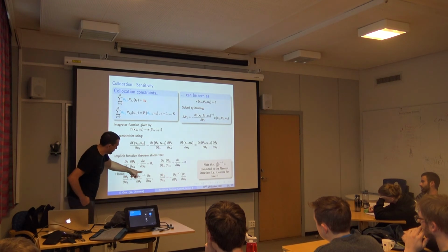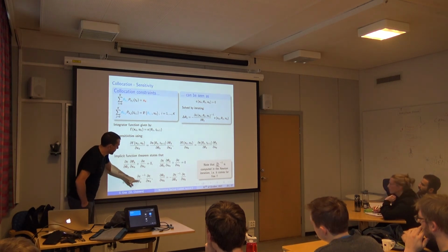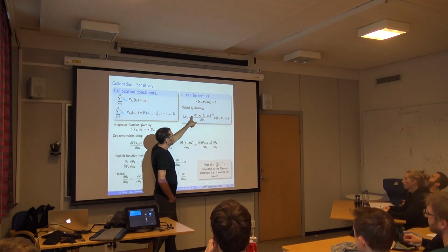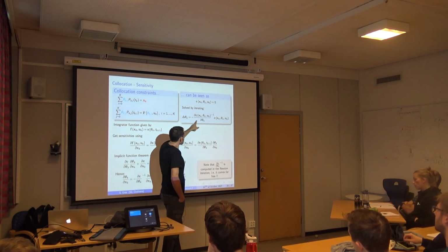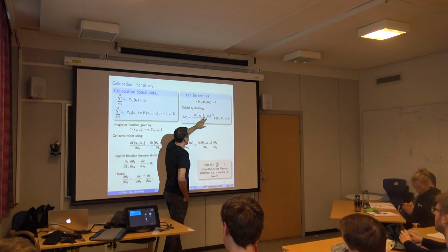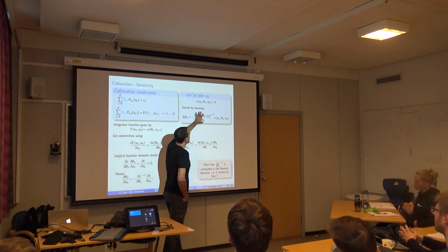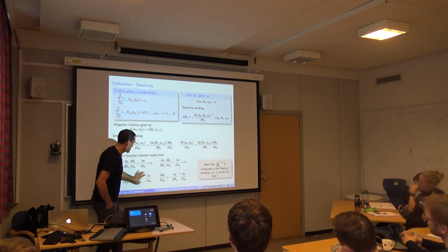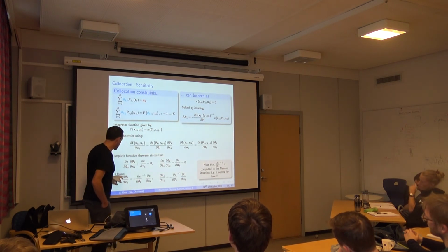Then you have to form this matrix and invert or factorize it. The good news is, in order to find your theta, you have run Newton, and you have basically ended up with a factorization of this matrix at the theta you are interested in. And this thing here, you can keep it and plug it in these formulas here and get these sensitivities pretty much for free.